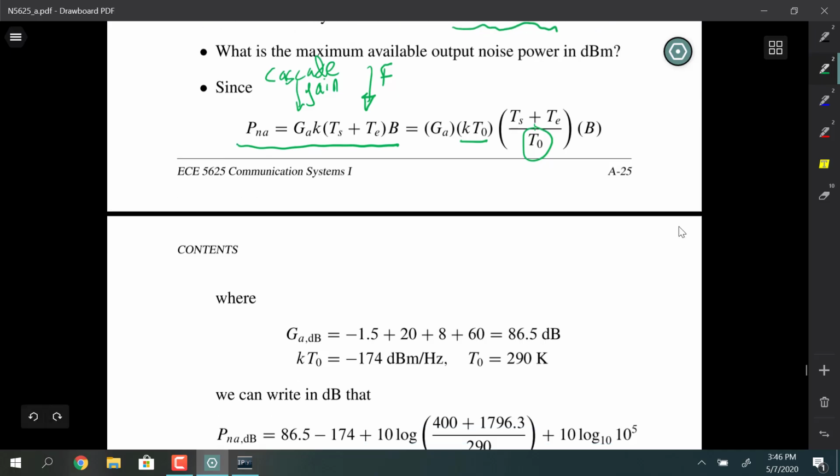And when you do that, and then you want to do everything in dB, then you can, because we've got multiplication going on in here. Now what we can do is, rather than multiplying all those numbers out and finding what 10 log base 10 is, we can just take the gain in dB by adding up the gains of the individual elements in the cascade.